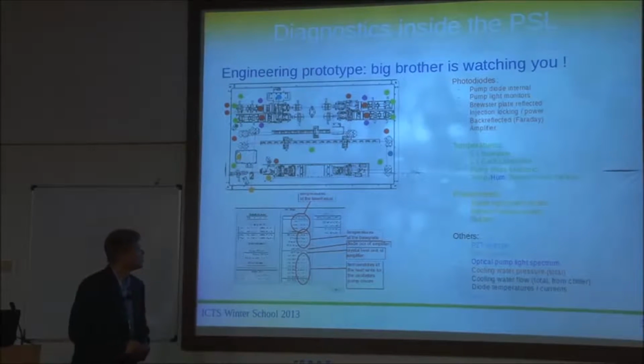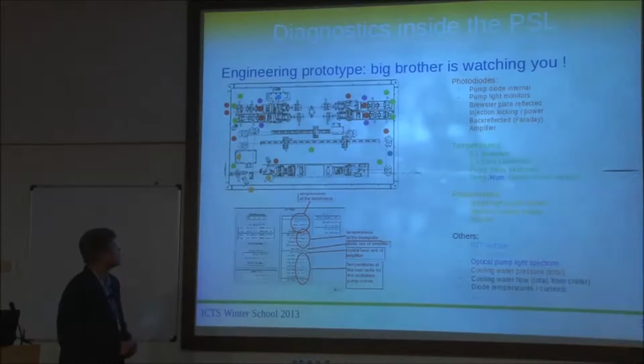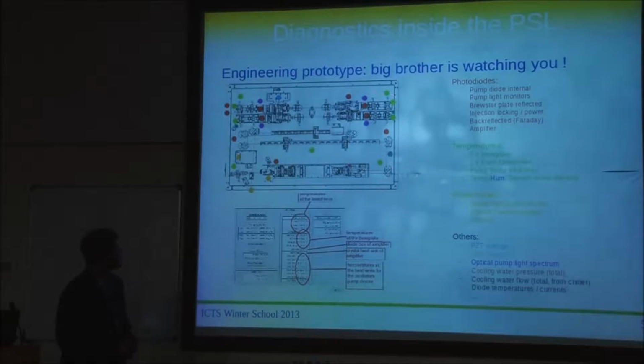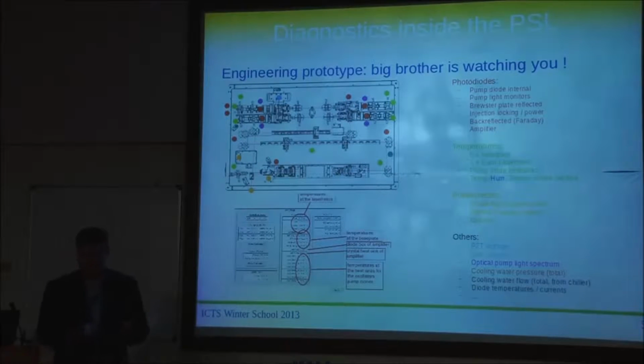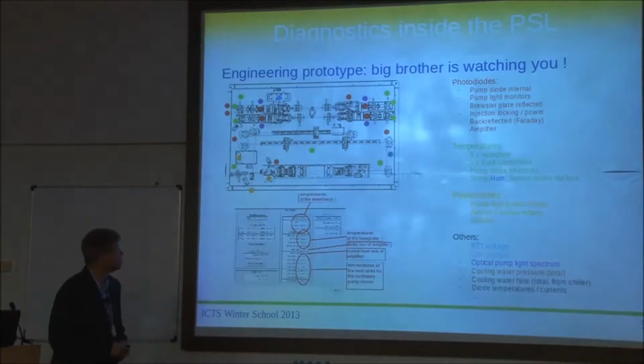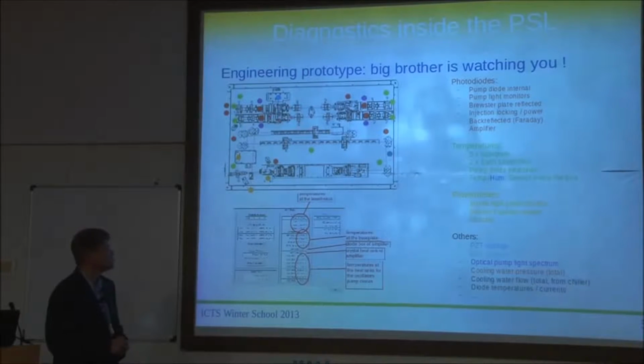But it's not only photodiodes, we also added some temperature sensors. So we put them on the base plate and monitored how the thing shifts thermally, whether there are some structural things going on and so on. And of course, we also wanted to monitor the temperature of the laser heads themselves, because they're kind of the critical component. Overall, it's a kilowatt of pump power going into that system. So of course, we wanted to know if that light heats something up.